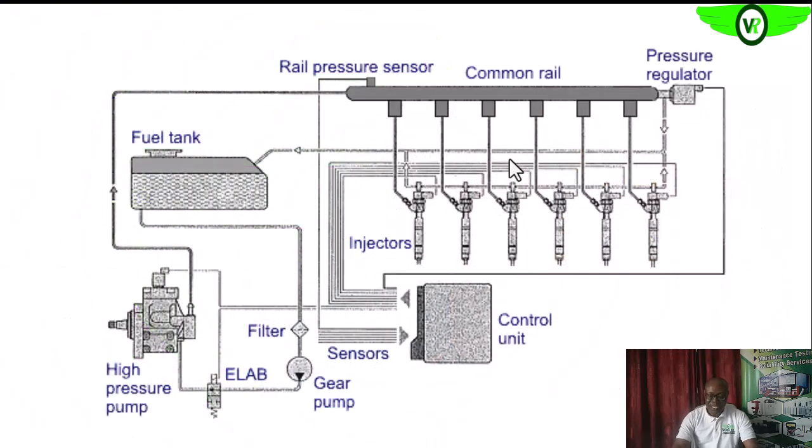So this is a kind of summary of the fuel system, okay. So here we have the tank. From the tank it goes through the fuel pump, okay. Then we have the manual priming pump, then to the main injection pump also, okay. The main injection pump is meant to pressurize the fuel to the level that it will be able to break all of these nozzles.